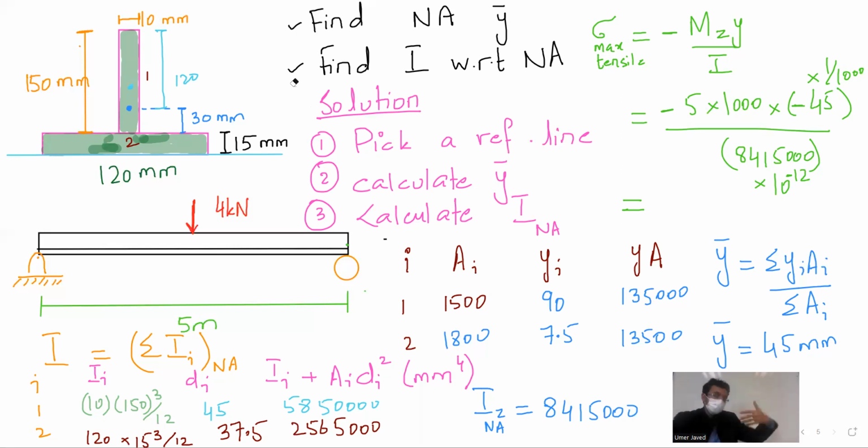So we are going a little further. Look, when you are putting a load like this, this is a beam. I keep on telling you that you will have bending stress. That is fine. But the next topic will be shearing. When you are putting a load like this, all these fibers also have shearing between them.